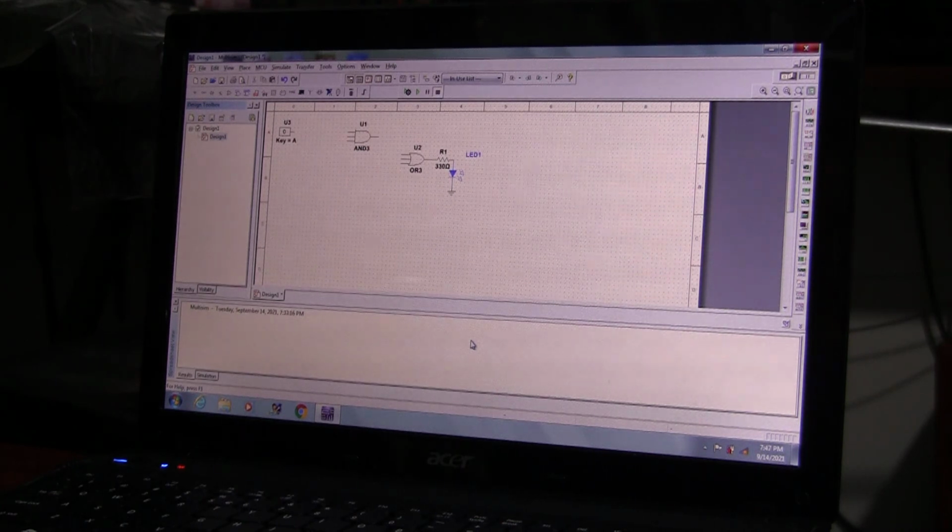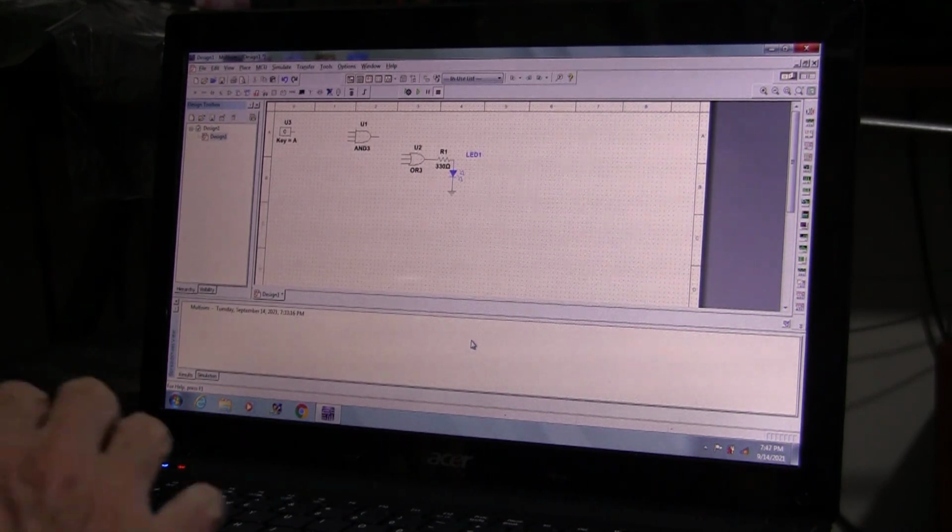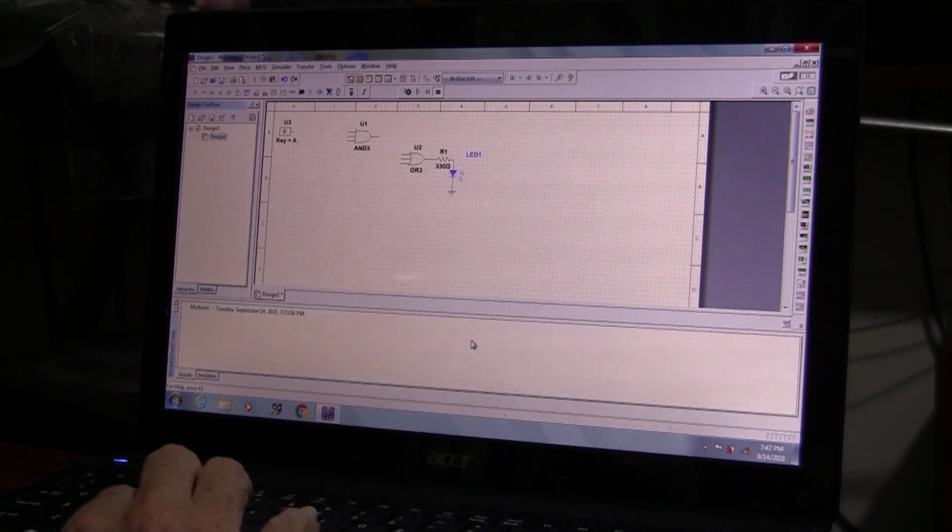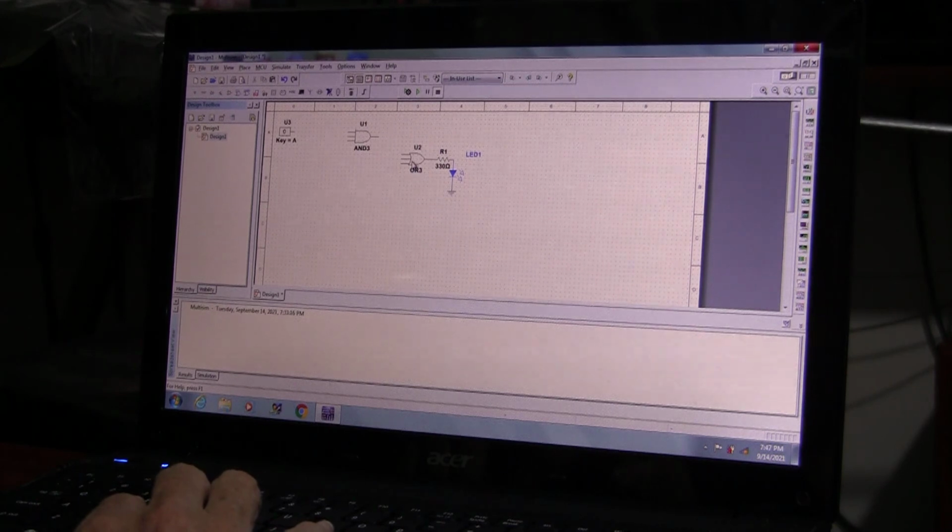Now, to connect up these circuits, we need to have 3 AND gates, 3 NOT gates, and we need to connect them to our OR gate. A big mistake students make is not to connect all their A's together, all their B's together, and all their C's together.